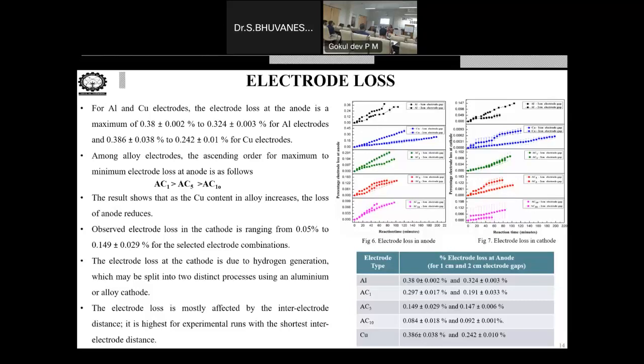Okay, because compared to aluminium electrode, actually iron is most commonly used, but it has a lot of hydroxyl formation problem. Okay, loss will be more easily. Every time we have to replace the electrode. In order to overcome that, people went for aluminium. Aluminium is cheap as well as it has not much dissolution compared to iron, and it is not harmful also. Okay, because of that, people started moving to aluminium.